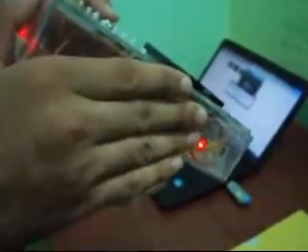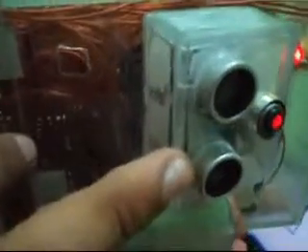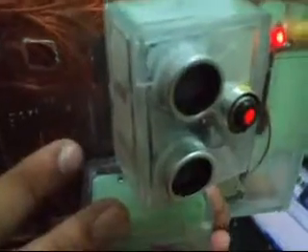When the user tilts the device to point it towards a point up to which the distance is to be measured, the ultrasonic distance sensor at the bottom of the device also experiences the same amount of tilt. So it will measure the slant height of the device above the ground, and the calculation data of the distance based on the slant height would be wrong. So for this purpose, the ultrasonic distance sensor is mounted on a servo platform. This servo platform can perform the relative motion with respect to the chassis of the device.